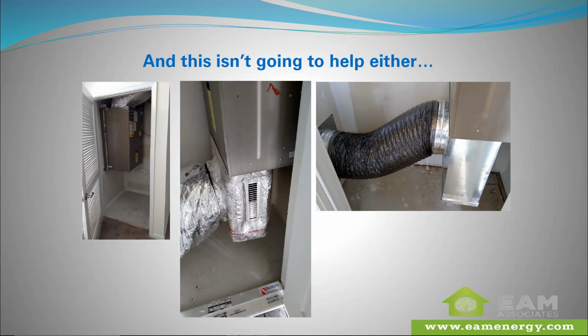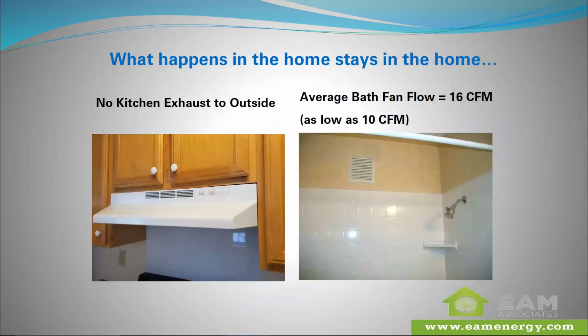This was a picture on the right of before they had added insulation. So some of the units, even before they cut the returns in, because they were letting people put items in these closets, were already causing damage to the air coil here, to that piece of ductwork. And again, introducing moisture from the outside in.